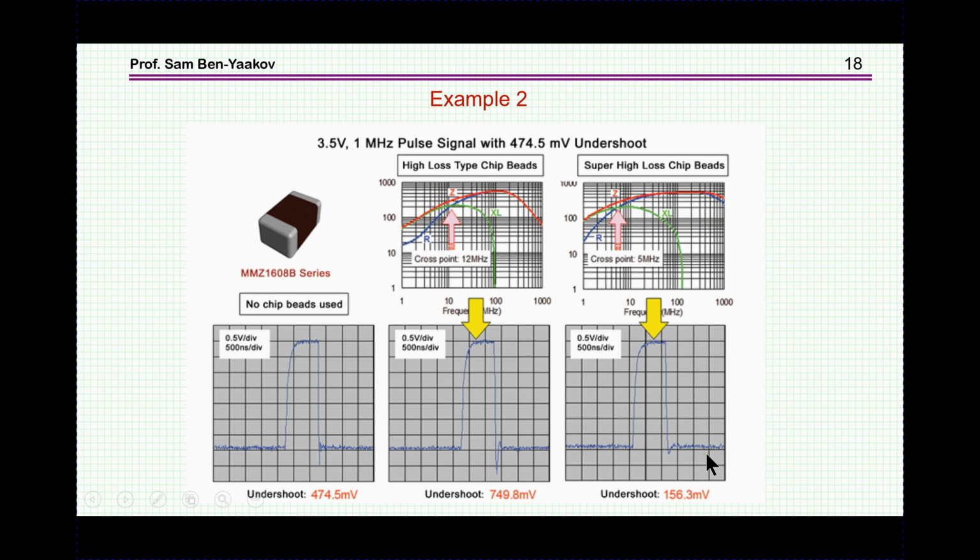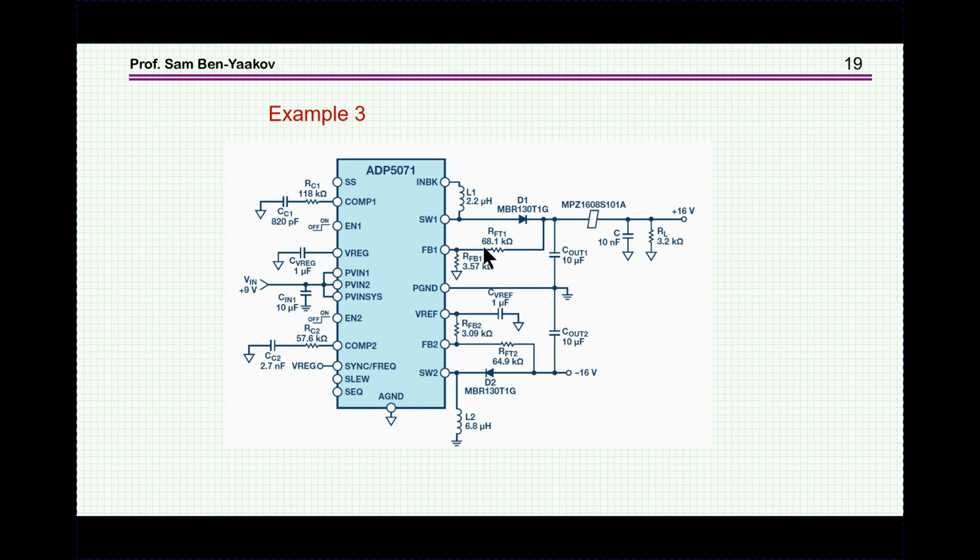On the other hand, if the resistive part is dominant at the frequency of interest, this is the frequency content of the spike, then this spike is attenuated quite a bit. There's a little wiggle here, but there's no spike. So this one is really helping. This one is making it worse. This is frustrating, but that's the situation.